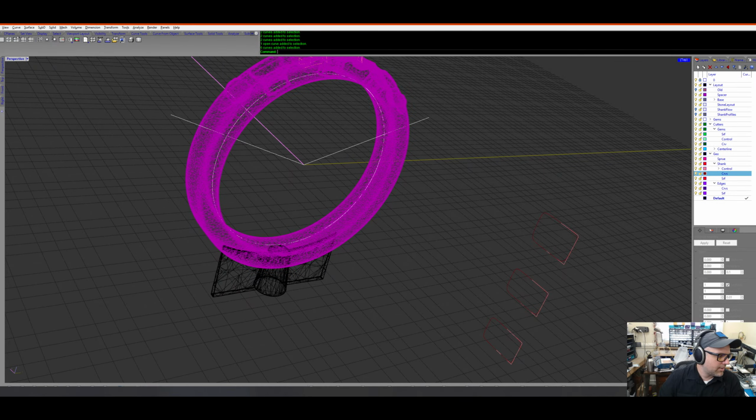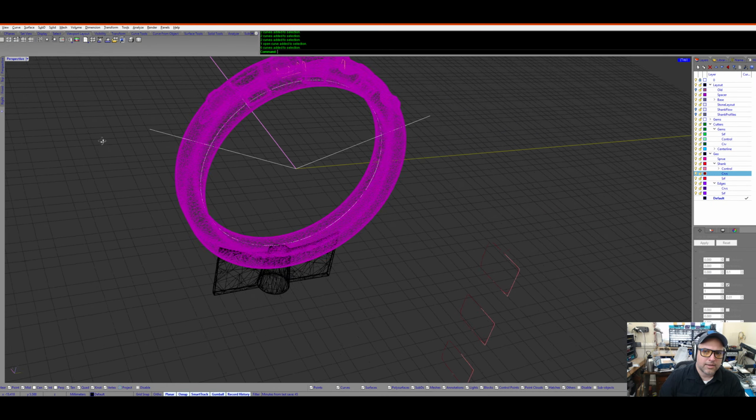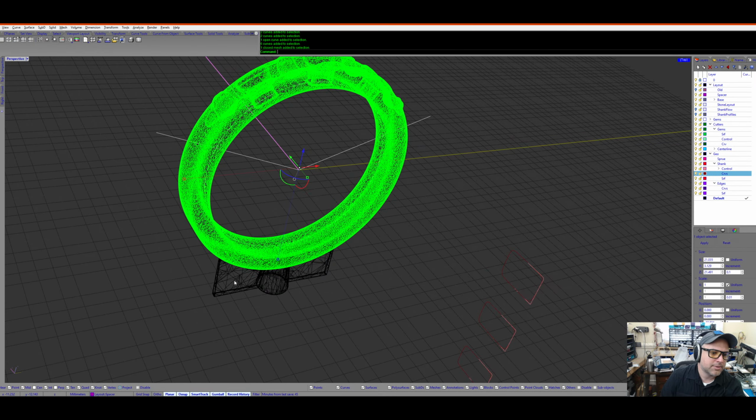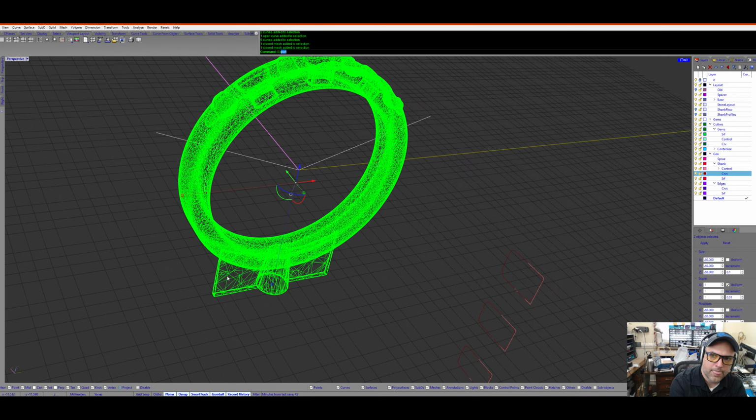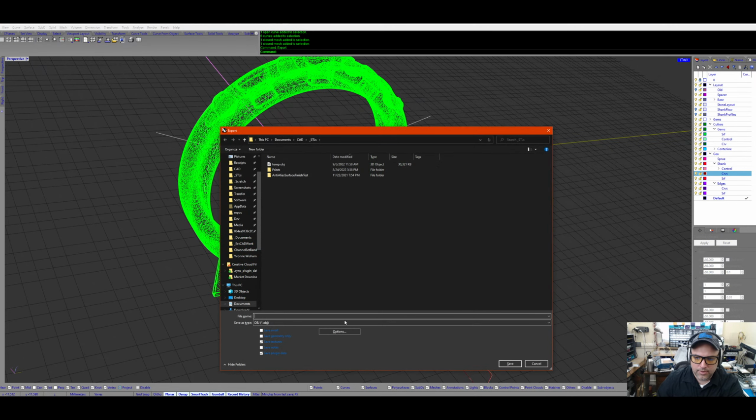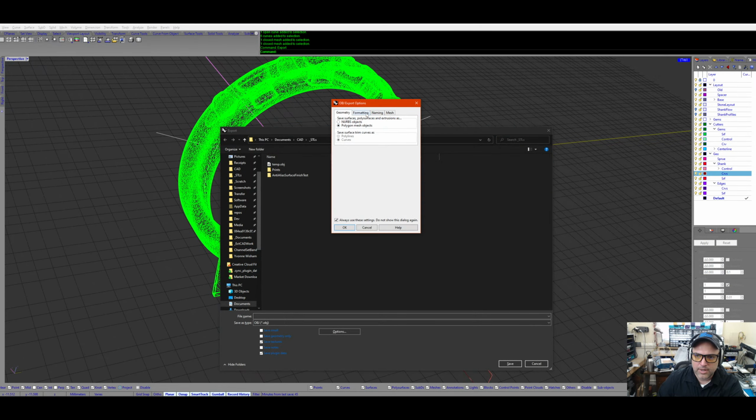There's one more gotcha that I didn't think of. When we did the export, under these options, there was something else, which is map Rhino Z to object Y. In a lot of programs, in Rhino, Z is our up and down.